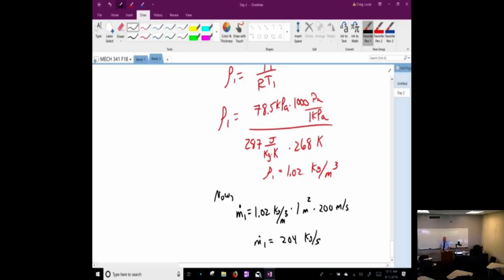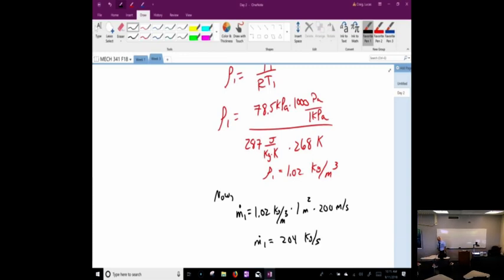Now, can't you do the same thing for temperature? We can't, we don't know the area. Wouldn't that cancel out then? Not constant velocity. Density is going to be the same throughout, right? No, because the pressure changes in your control volume. And then it's m out. There we go, conservation of mass: m dot 1 equals m dot 2.